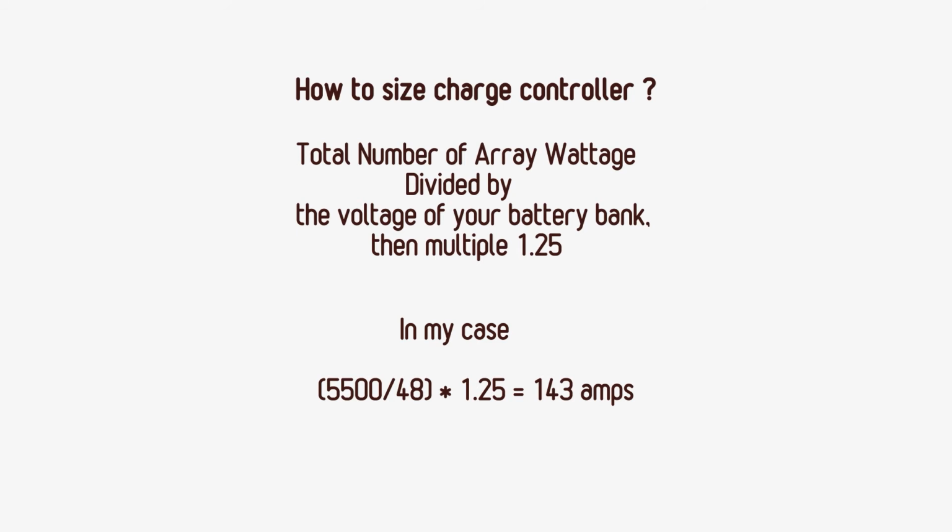And so the way you size a charge controller is you take the total array wattage divided by the voltage of your battery bank, then multiply by 1.25. This 1.25 is just for security.